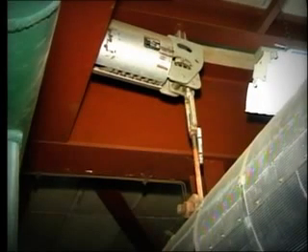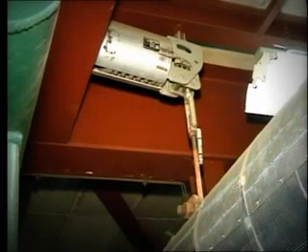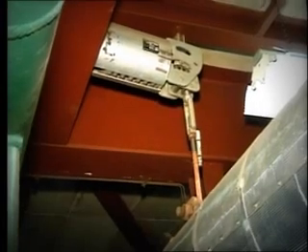The pipe hangers and supports are designed to be flexible and allow movement of the pipe under expansion forces. The operator should make himself aware of the normal position of critical pipe hangers. Often an indicating pointer is fitted to allow this. If a hanger does become jammed and prevents the free movement of pipe, physical damage may occur to the pipe itself or to other supports.